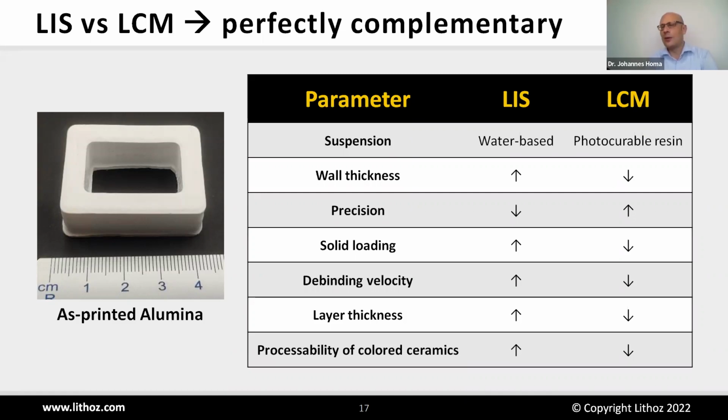And as I said, wall thicknesses can be much thicker and bigger. Precision goes down a little bit, but you can also have a higher solid load because it's just water-based, and rather low binder content at the end, because you are already evaporating the water and you're left with around 3% binder. So you can really debind very quickly. You can also say there is almost no need for debinding because there is so little binding agent